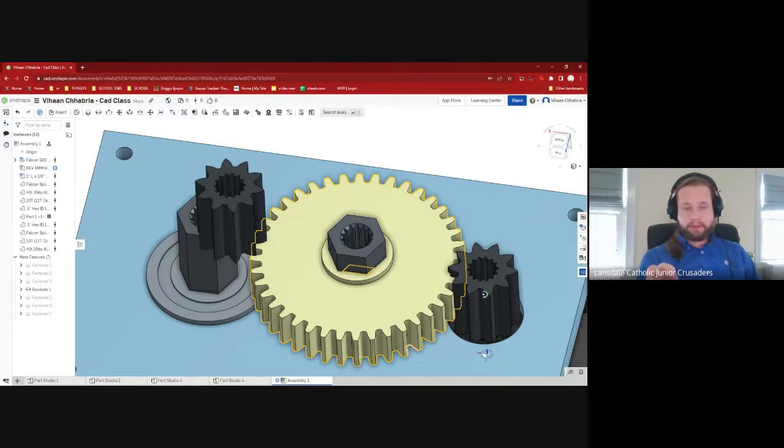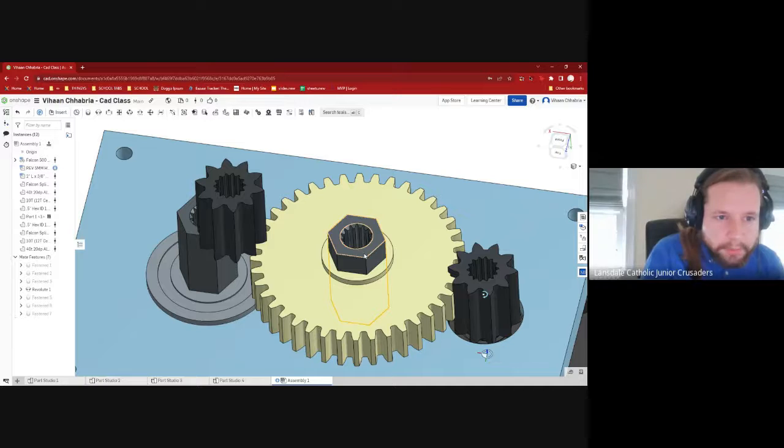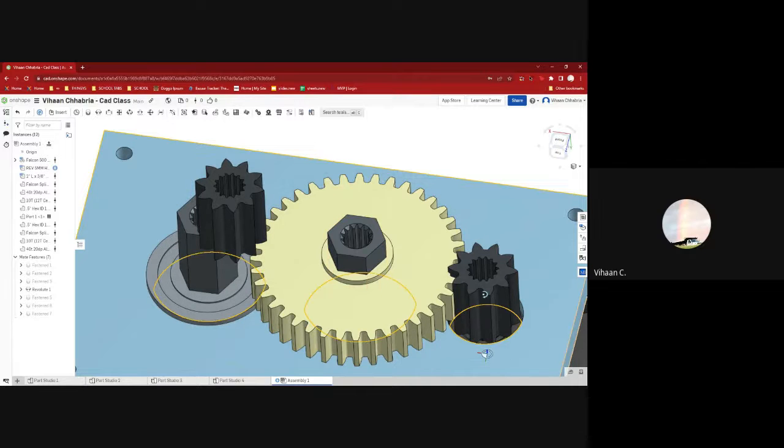Find a 48 tooth gear to put on there and find a 12 tooth gear with a 1/2 inch hex ID to put on the hex and continue your design. I will tell you now that those hex shafts that you have, those aren't really the ones you want. Which one would I use?